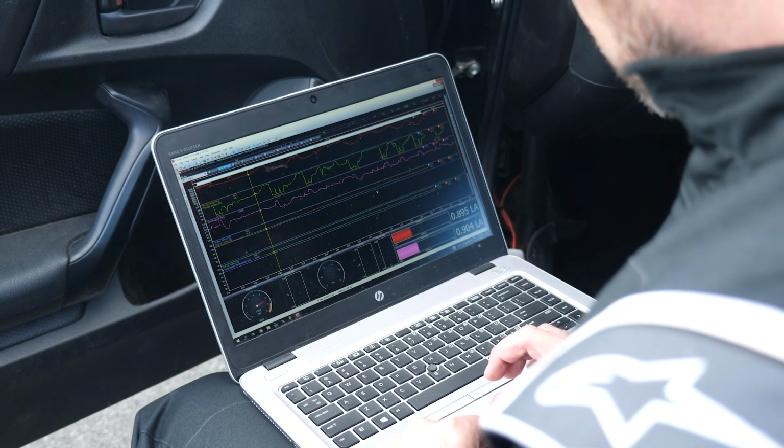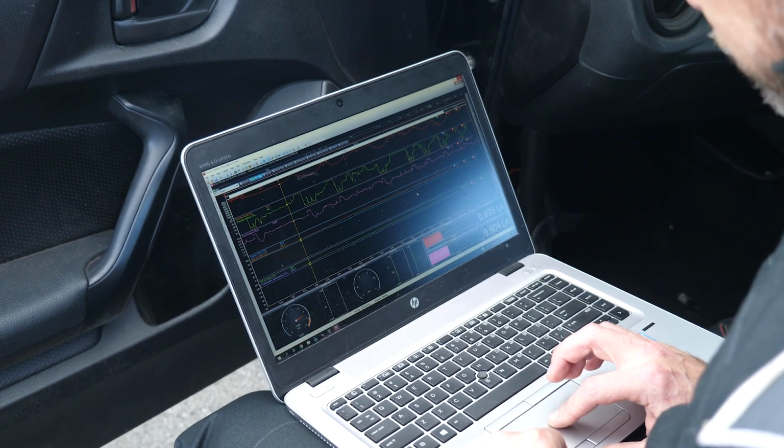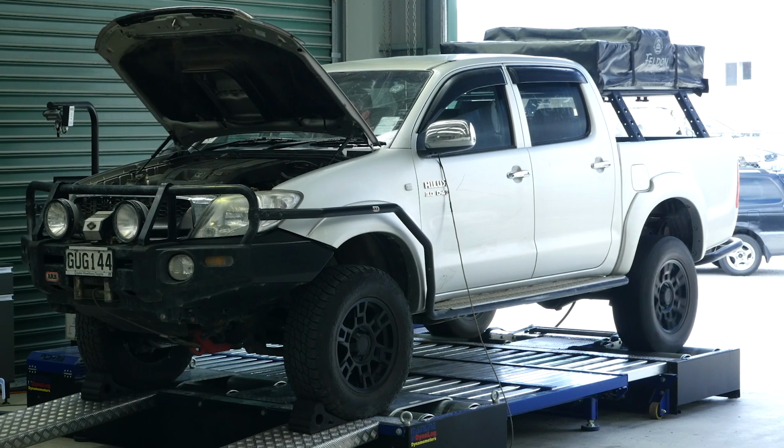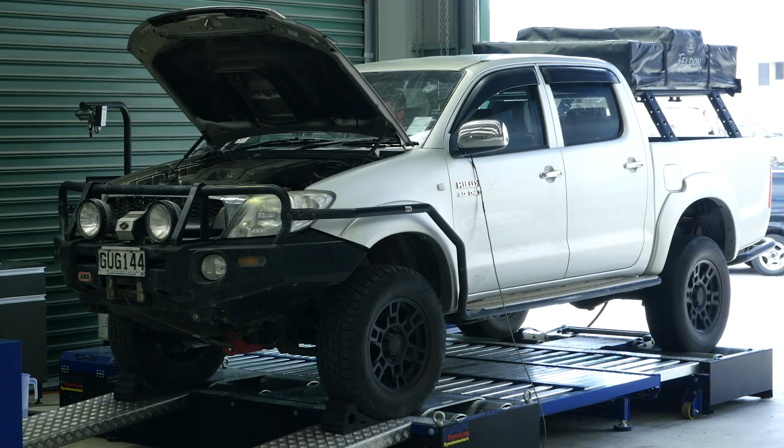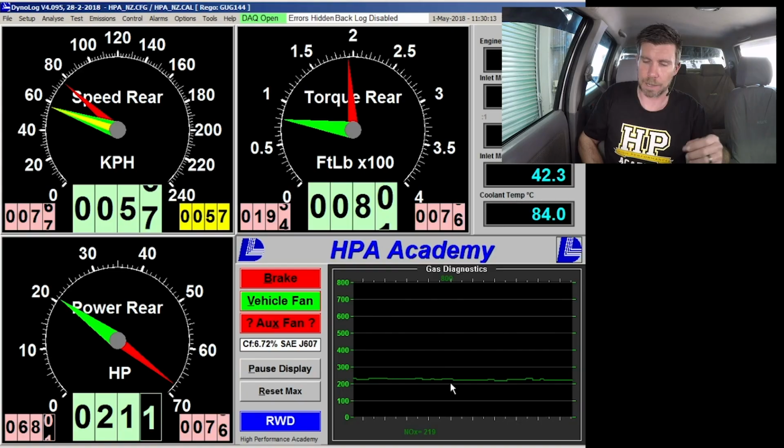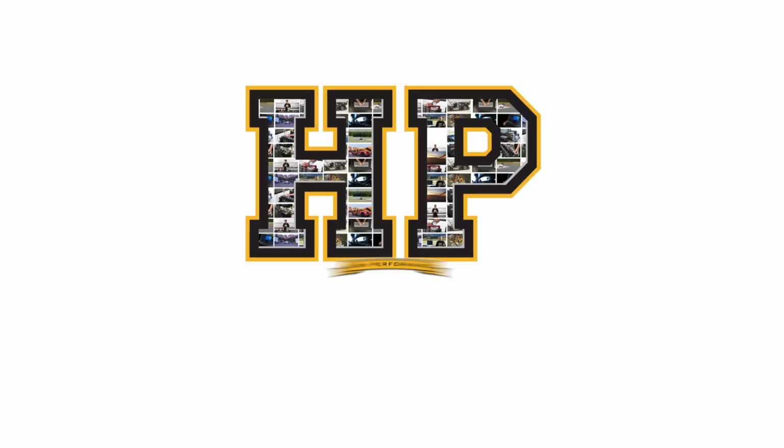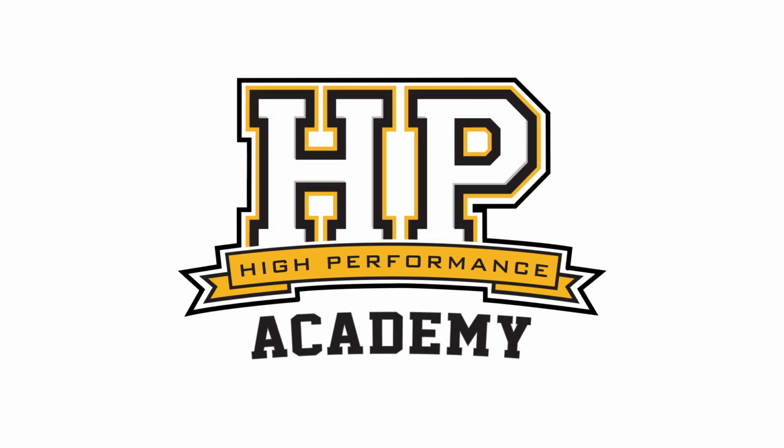We're going to have a look at some of the aspects that will affect our exhaust emissions from a diesel engine. In particular here, we're going to be using a 5-gas analyzer connected to our mainline dyno. And this is going to be showing us the oxides of nitrogen, or NOx, levels in parts per million.